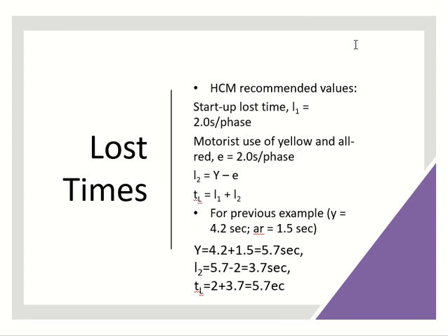You are allowed to enter in 4.2 seconds, right? But practically, if you are too far, you think that I should stop. So any vehicle which arrives within 2 seconds of this time is prepared to go. Any vehicle which arrives after 2 seconds is prepared to stop.